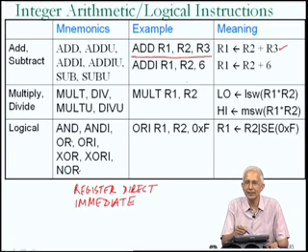There's also an add immediate instruction which can be used to add a value which you specify inside the instruction, such as 6 in the second example, to the contents of a register, with the result going into another register. So the add and add immediate instructions can be used to do addition on signed integer values, which gives you some indication that the 6 that we have over here could just as well have been a -6, and then this would have been adding -6 to R2.